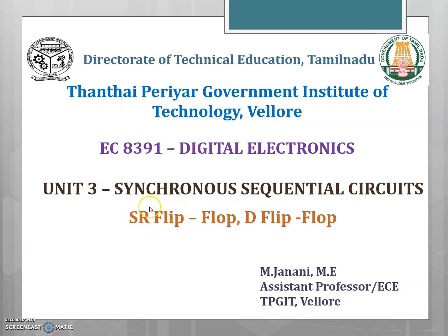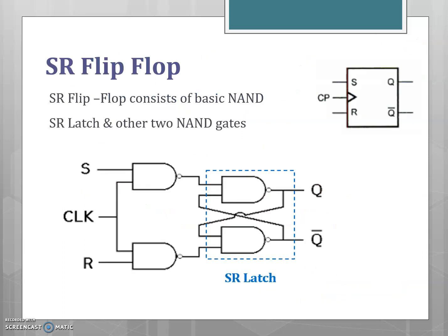Hello everyone. In this lecture, I will be discussing SR flip-flop and D flip-flop. A flip-flop is a basic memory element capable of storing 1-bit information, either logic 0 or logic 1. This flip-flop is a latch along with the clock, so it operates in synchronism with the clock.